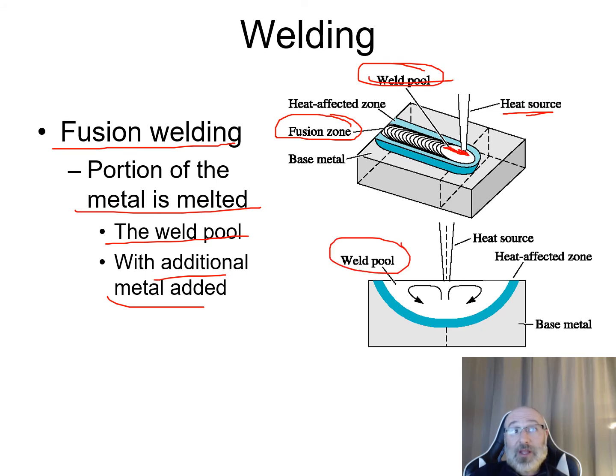We're melting that metal right there, and we can see there's the heat source in the 2D view, and then in the blue right here, this is now our affected heat zone right there. So when we're talking about the size of our affected heat zone, again, that's going to be back to a couple of those factors we just talked about before, one of which being the temperature of our heat source right there, along with the shape and size of the weld bead and the area that we're filling.